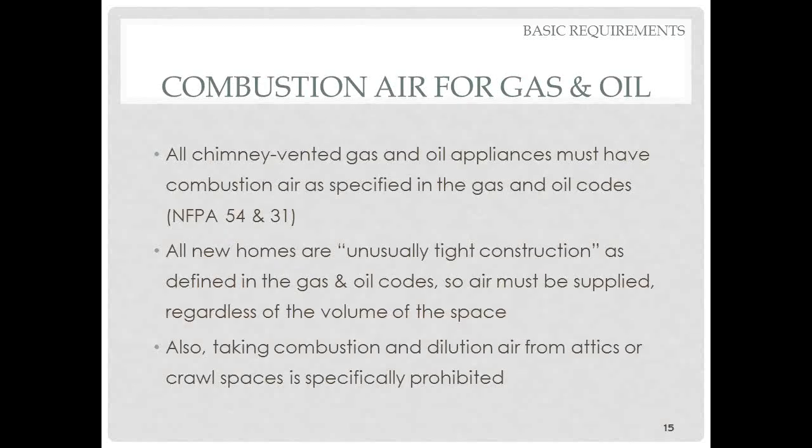There's also a combustion air requirement for gas and oil. All chimney vented gas and oil appliances must have dedicated combustion air. What this means is that there needs to be some sort of hole or ductwork from the outside to either the burner or the room that the boiler or furnace is in. That combustion air has to be provided as specified in the National Gas and Oil Codes, NFPA 54 and 31, and there are a couple of additional restrictions.